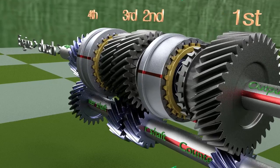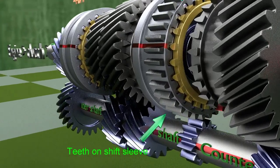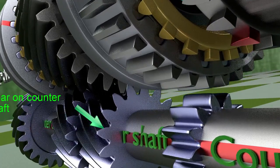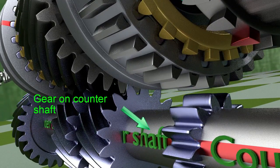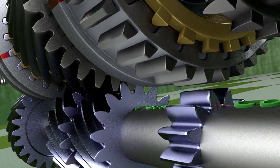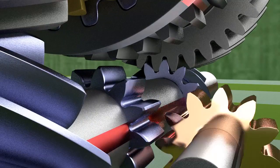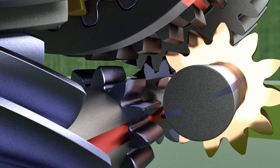For reverse gear, teeth are provided on the shift sleeve and a corresponding gear on the counter shaft. These gears are not meshed directly. To connect them, an idler gear is used so that the direction of rotation can be reversed.